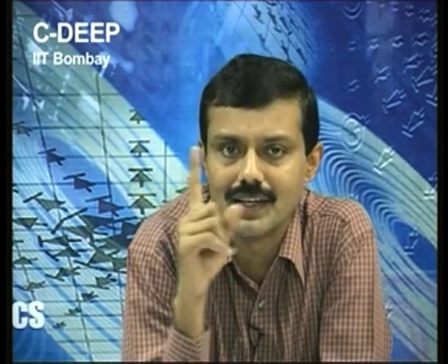Now what is the peak value of the phase voltage that I can get using the space vector? We found that for 0, 0, 1, in other words, only the upper device of phase A is on, the length of the space vector is VDC, and for this position the y component is 0. We have only the x component.